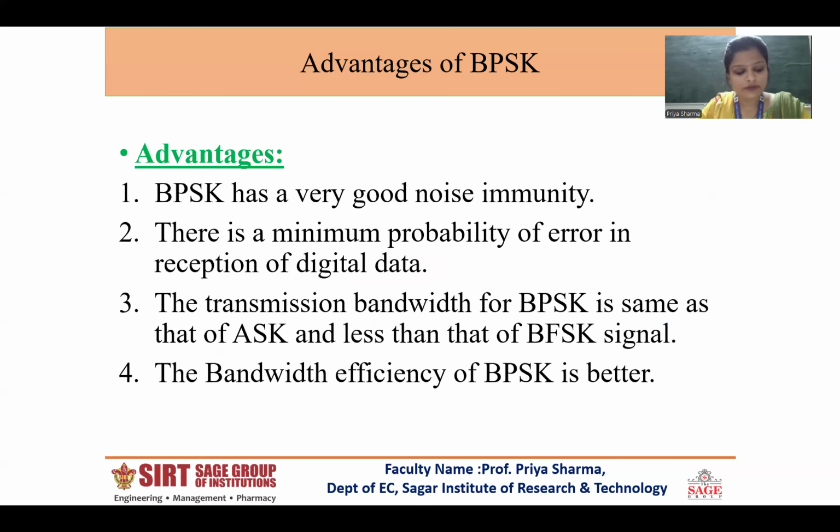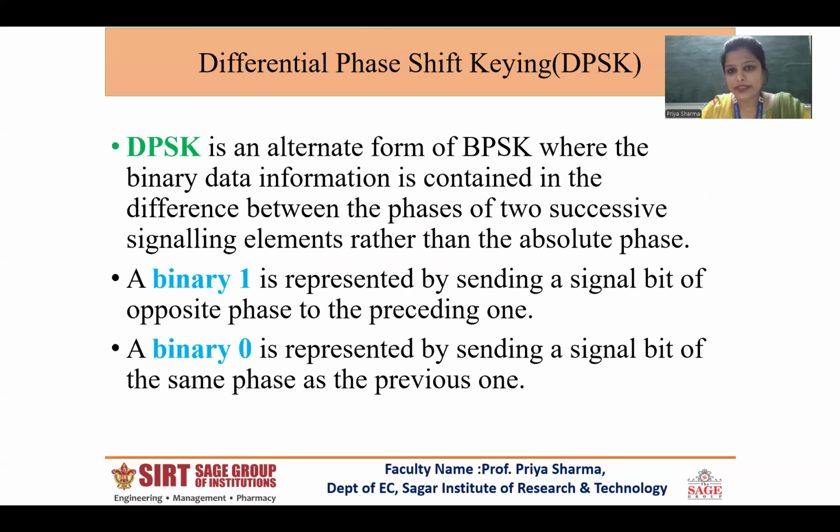Coming to the advantages of BPSK signal, BPSK has very good noise immunity. There is a minimum probability of error in reception of digital data. The transmission bandwidth for BPSK is the same as that for ASK and less than that of BFSK. The bandwidth efficiency of BPSK is very good.